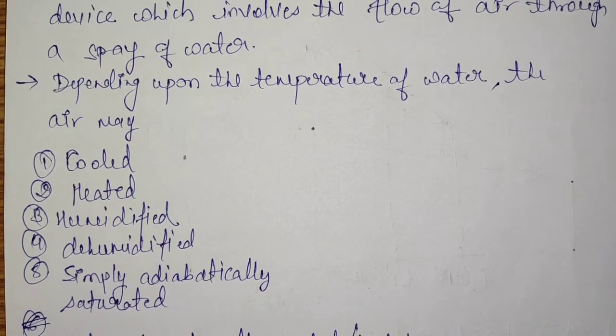First is cooling, second is heating, third is humidification, fourth is dehumidification, then simply adiabatic saturation. Which process will take place for the air will depend on the temperature of the water through which the air is passing.